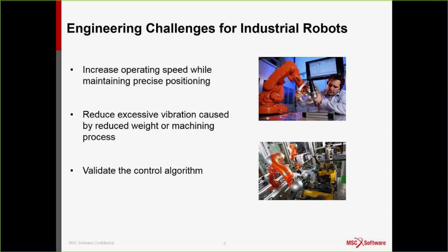For example, if you apply a bigger motor, or a larger acceleration to certain components, or you try to lightweight your robot to make it faster with the same power source, you can sometimes have problems like excessive vibration, deformation, or even gear rattle effects.